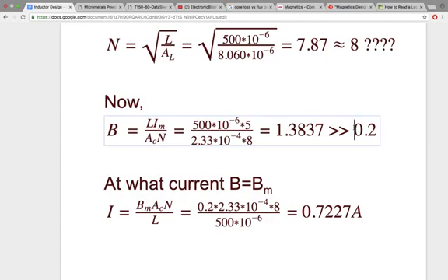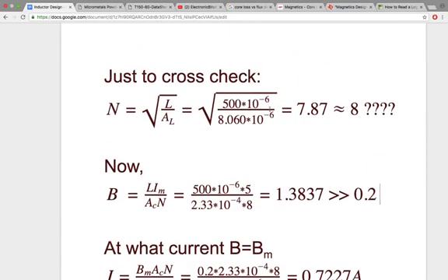But if you put it in a real power circuit where current starts flowing, you will see the problem. You will think that the circuit should operate correctly, but it doesn't. So it's very important not just to get the inductance value; it is also very important to get its current rating. Here this AL value has completely failed. We cannot rely on this.